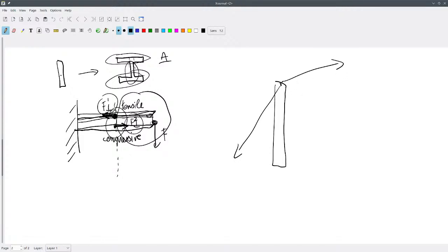In particular, it's a utility pole that is at some corner. So these are both horizontal wires and tensions that connect the cables from one street to the perpendicular street. And then there's what is called a guy wire, which is connected to the ground here to prevent this pole from just toppling over in that direction, right?